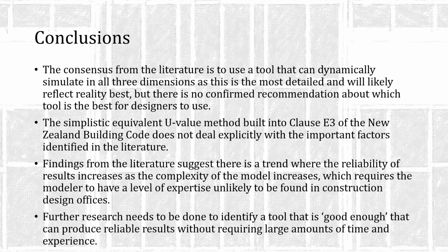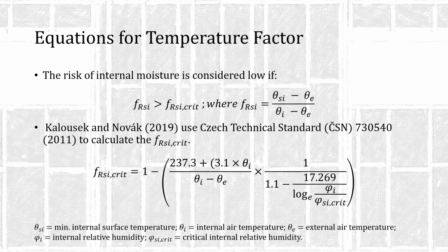But if the clause E3 method is too simple and a 3D dynamic tool is too complex, what tool is best suited for designers to use that could reliably assess the risk of condensation without requiring large amounts of time and experience? Further research needs to be done in this area to identify a tool that is good enough. Just for reference, the equations used to calculate the temperature factor and critical temperature factor are shown on the slide.